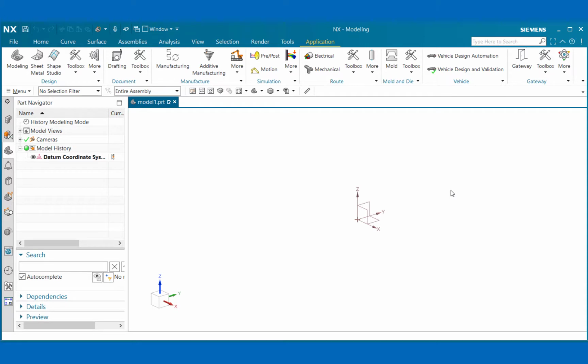Product and Manufacturing Information, or PMI, is an application that provides tools to add dimensions, annotations, and symbols to a 3D model to document products in a 3D environment. Basically, you are taking 2D drafting measurements and notations and placing them on a 3D model, which is then delivered to a customer or manufacturer for review. With this approach, there is no need for drawings.